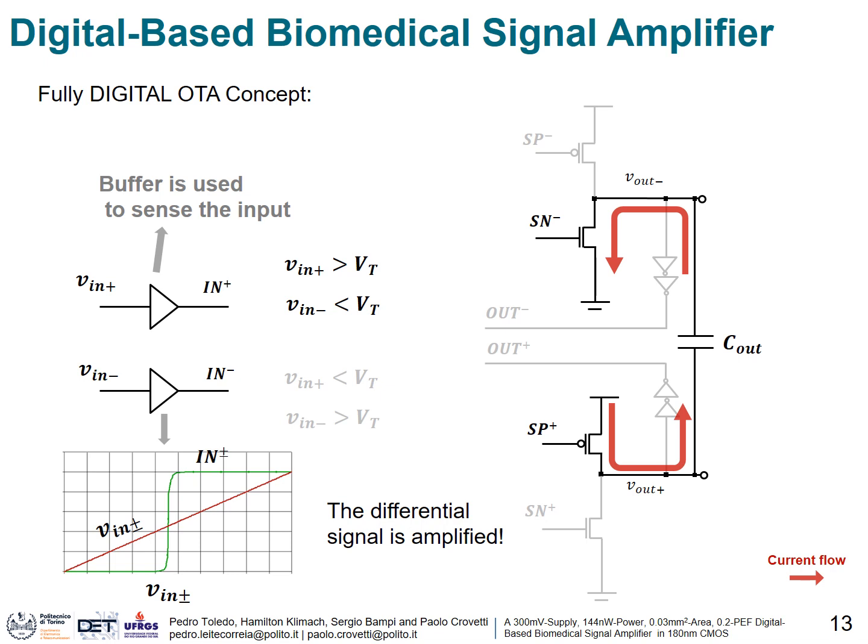When Vn plus is larger than the threshold Vt and Vn minus is lower than Vt, as you can see in this slide, we can adopt as the output stage two 3-state inverters to charge and discharge the voltage of the output capacitor according to the desired voltage polarity.